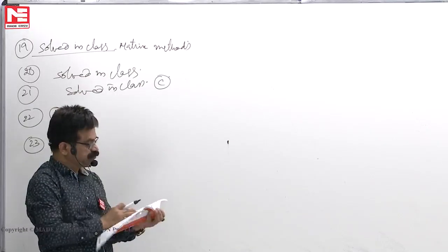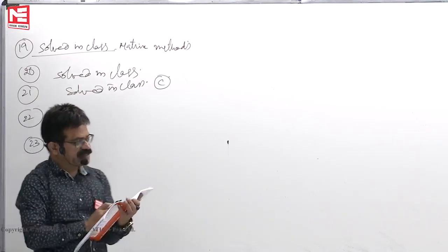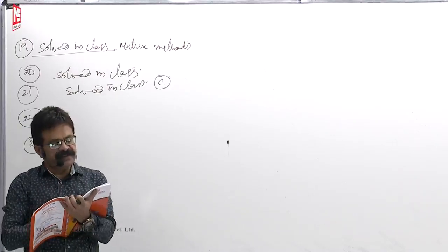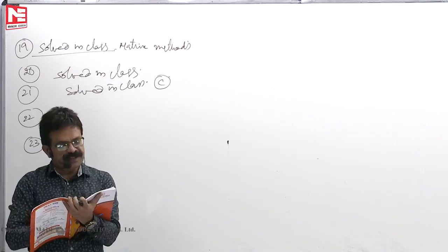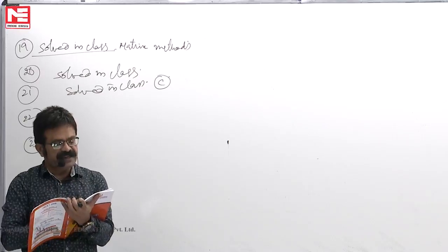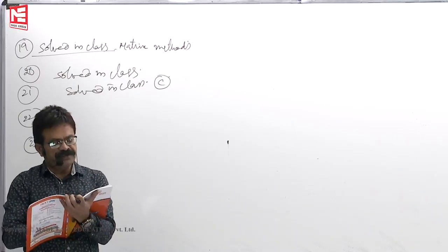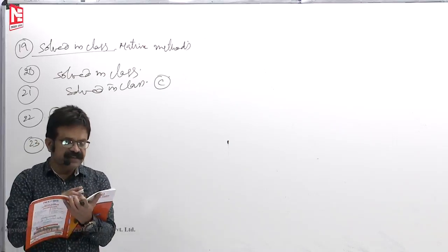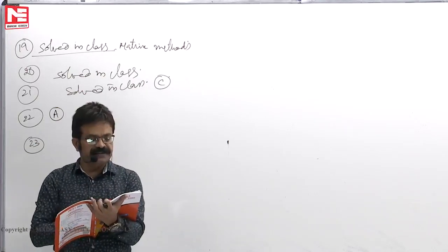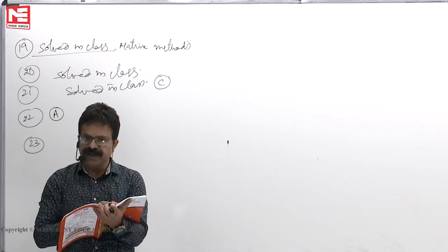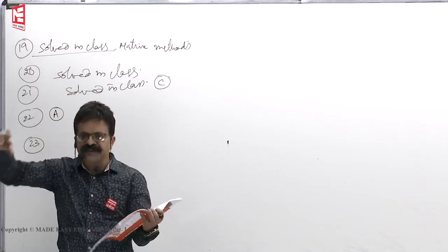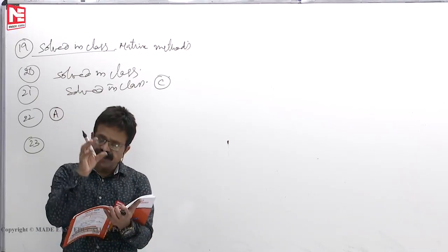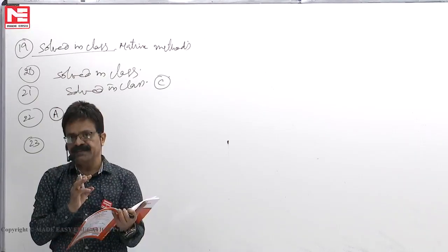23. Force method of analysis is not convenient for computer programming. I gave you the reason. Reason: bandwidth of the flexibility matrix is much larger compared to that of the stiffness matrix. Reason is also correct, but that is not the correct explanation for the unsuitability for computer programming, because the choice of redundants is not unique.